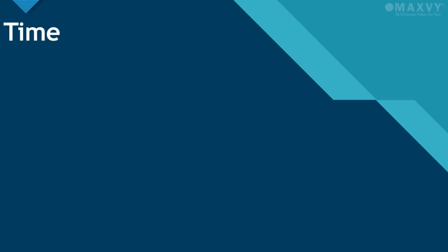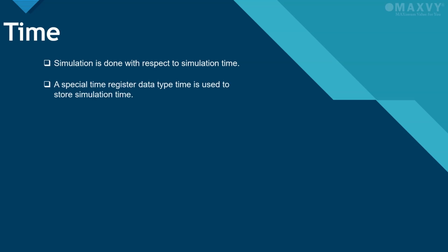Let's move on to how Verilog handles simulation time. This is crucial because all our simulations are based on time progression. All simulations in Verilog are performed with respect to simulation time. It's the basic backbone of any simulation progress. Verilog has a special data type specifically for storing simulation time called a time register. The width of these time registers is at least 64 bits. This allows a very large range of time values, which is useful for long simulations.